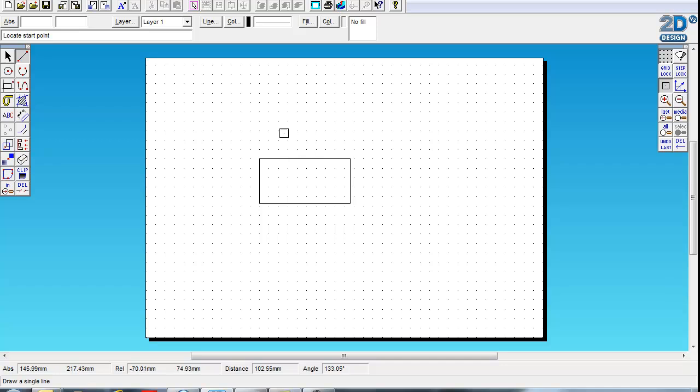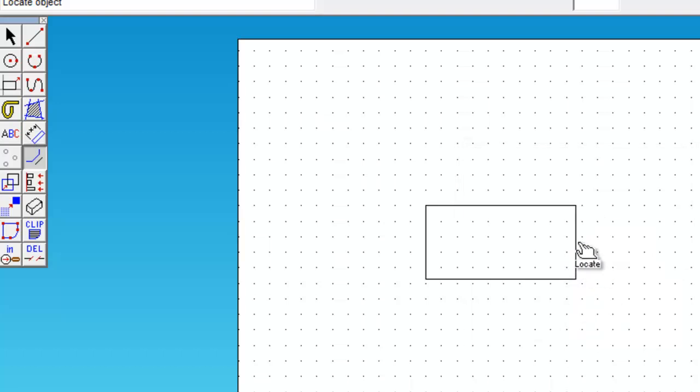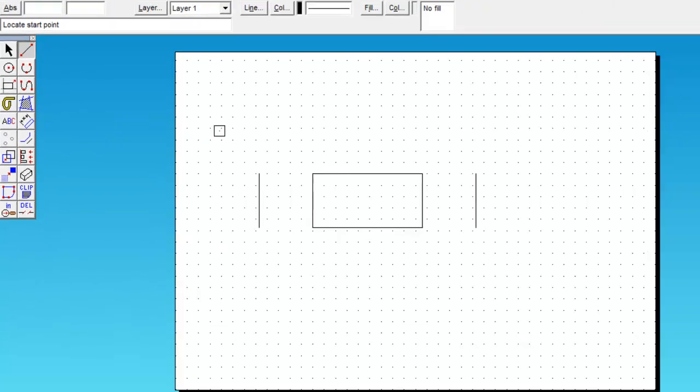So I'll continue now to create the rest of the cuboid net. Again, choose the contour tool. I am going to make one end of the cuboid a square. So I'm going to make it 47 again, because this was the same distance from here to here. Click OK, and again click on both sides to expand the net out.